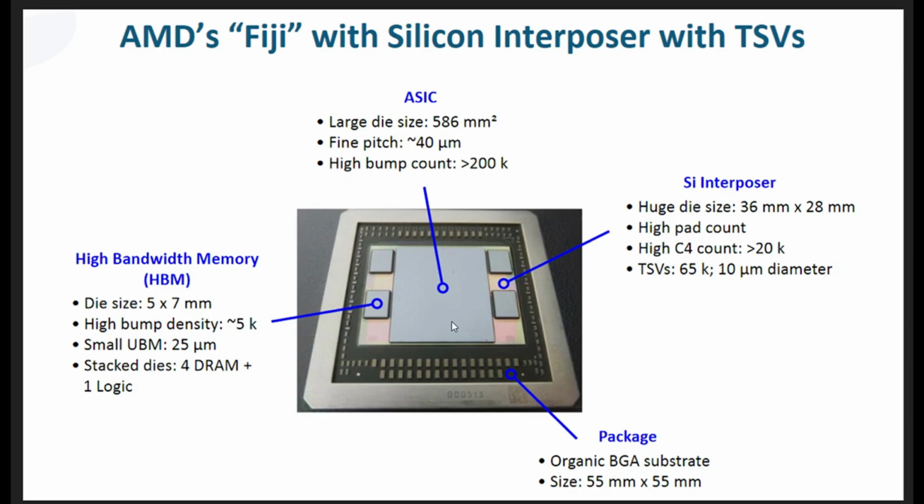There are 1 or 2 differences though. As you know, a GPU is filled with transistors and will generally be fabricated on the very latest manufacturing technology, because performance and power is critical. A silicon interposer, on the other hand, we are mostly talking about a dumb block of silicon. And so these are generally manufactured on older processes, for example 65 nanometers, and the reason for that is simply cost. It would be far too expensive to manufacture such a large slab of silicon on a new process. So using an older 65 nanometer process would get you better yields at a much cheaper wafer cost.